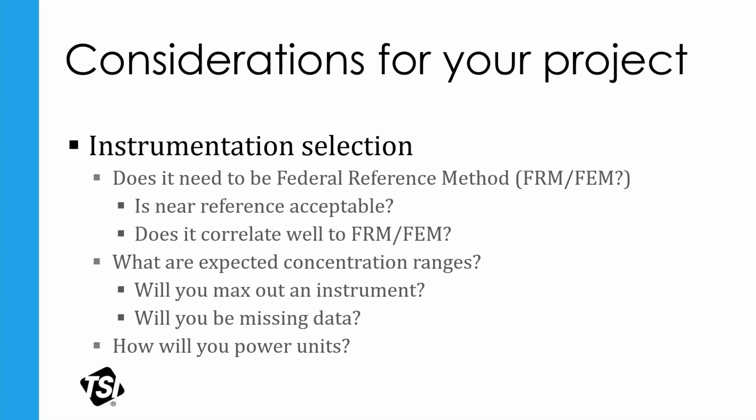Expected concentration ranges. If you're in an area that's already kind of dusty and arid anyway, there might already be a lot of ambient particulate. And so if you add that extra activity, are you going to max out an instrument with that digging activity, or with that construction, or any of those other activities? So take a look at that, because instruments can vary.